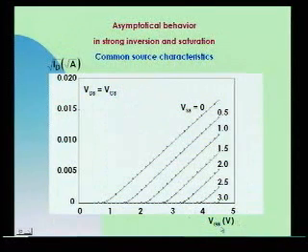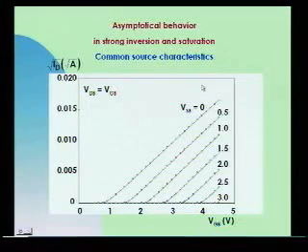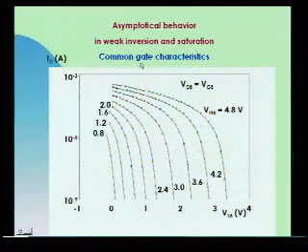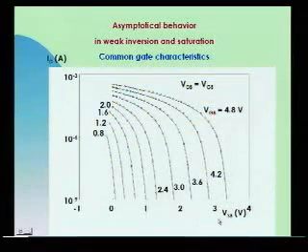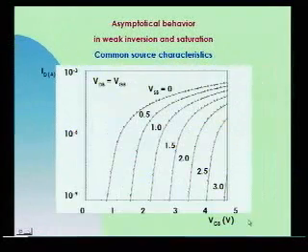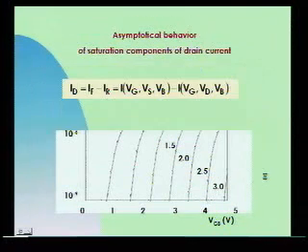It also applies to the VGB, okay? The common source characteristics. Then in strong inversion, I have this behavior. In weak inversion, both with respect to VSB or to VGB, I have an exponential behavior. This is no news for you, okay? This is no news for you, but